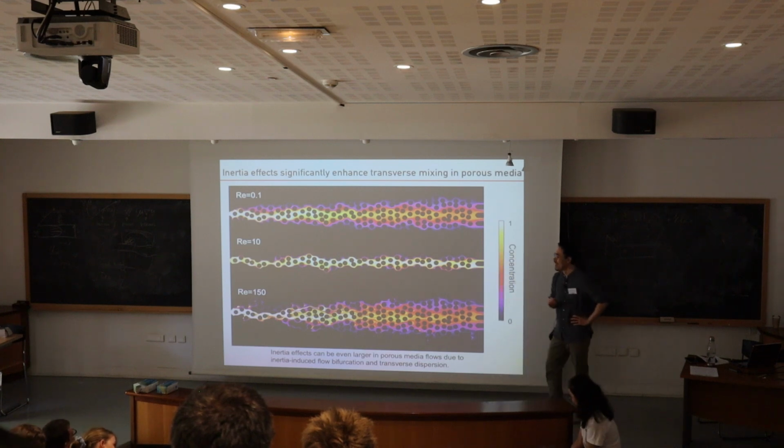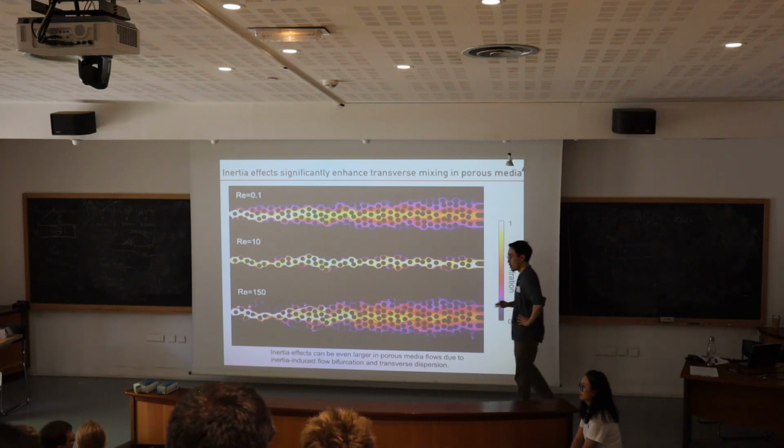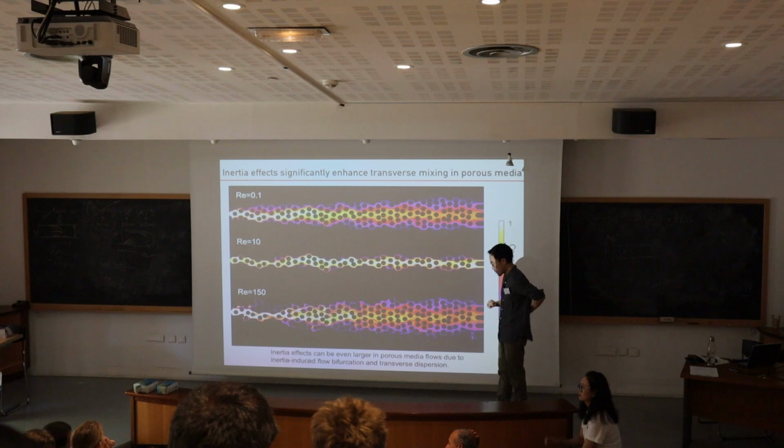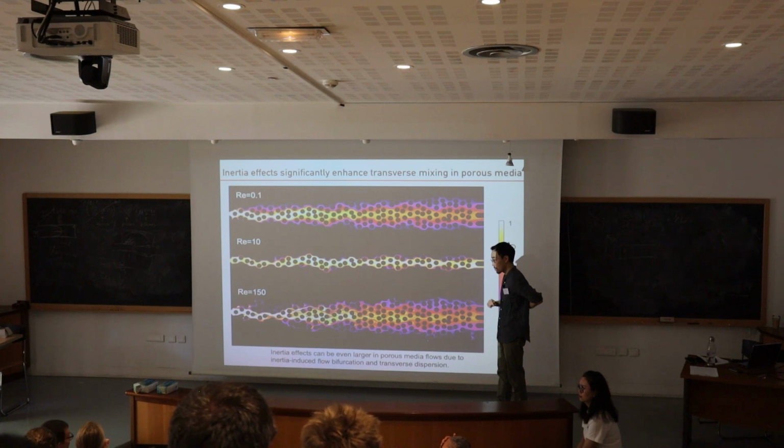Reynolds number, I mean, it's based on one cylinder in an infinite medium, and all this classification of turbulence is made on that. And in porous media, in many studies, they say, okay, you will have turbulence at a Reynolds number about 100. And there's some recent work from Lyon where they show that actually at Reynolds number 100, 150, you do have impact bed. You will have also signature of turbulence.